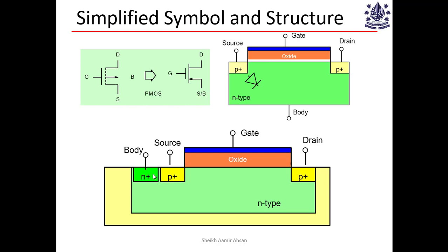All right. So when you have a p-type substrate, in order to create a PMOS in this p-type substrate, you have to create an n-type body, this thing, within which you can make your entire p-type MOSFET. That is very much straightforward. But you have to start with this n-type body. And this whole thing, this n-type body within which you make a p-type MOSFET, is known as an n-well. This has a name. It is called a well because you're creating a well within this substrate. Okay, you have to create an n-type well in order to make a p-type MOSFET.